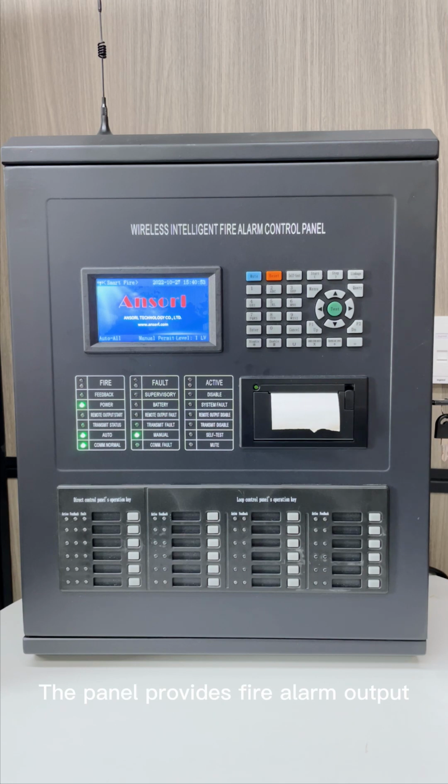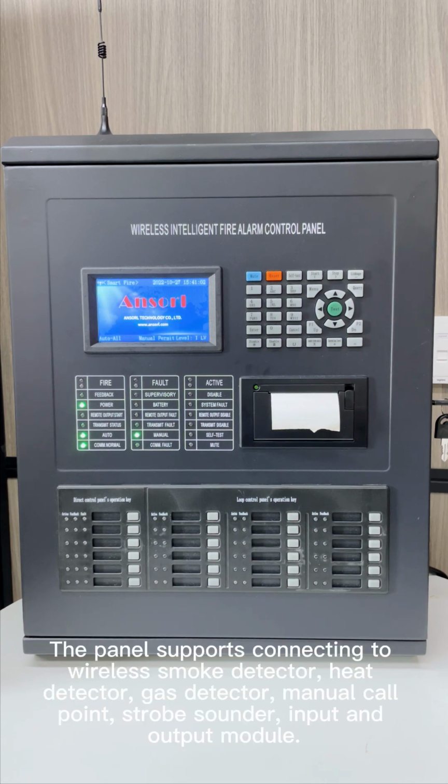The panel provides fire alarm output, sounder control output, fire relay output, fault relay output. The panel supports connecting to wireless smoke detector, heat detector, gas detector, manual call point, strobe sounder, input and output module.